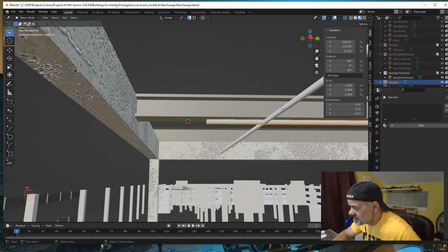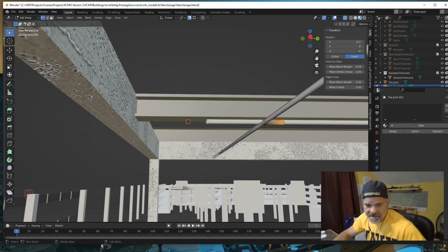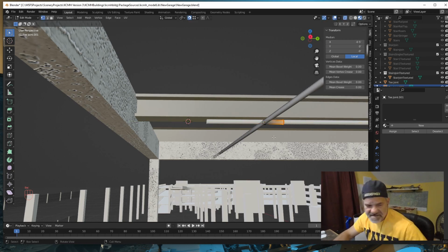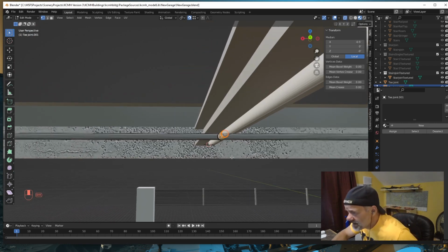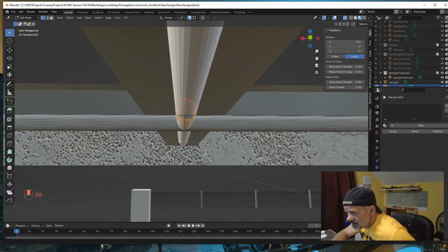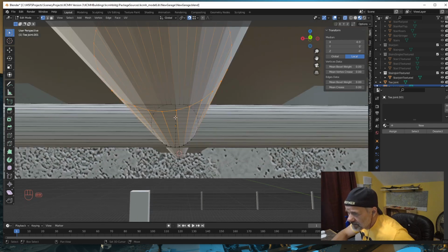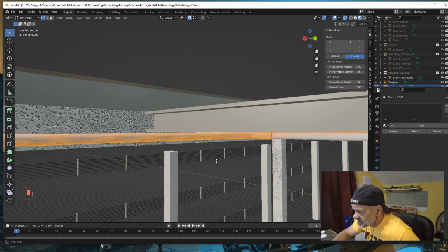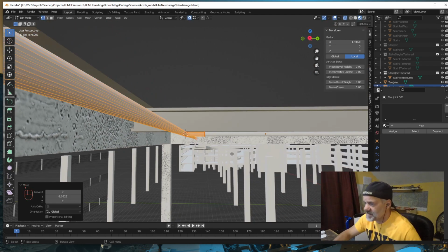And then get out of edit mode, select this pipe, and go into edit mode, and select these vertices. Vertices snap on, and move Y. Oh, wait a minute. Select all. Yeah, you see my mistakes that I make. Don't you love it? I want this one to be my active vertex. Now I want to select all my vertices because I'm moving my entire thing back over to here. So we're going to G, Y, then snap there. See how I did that?